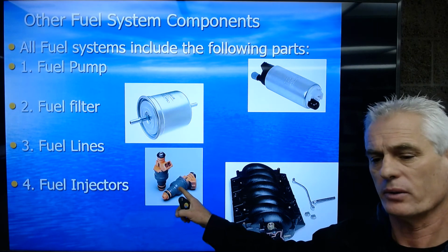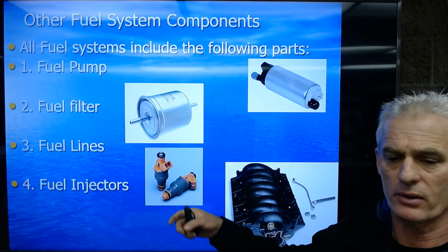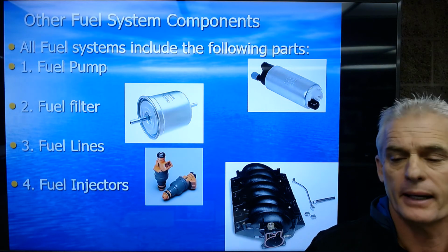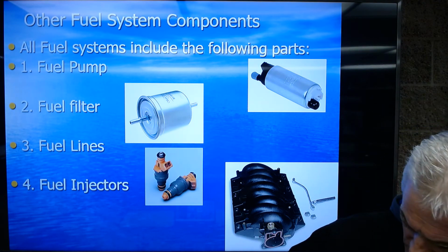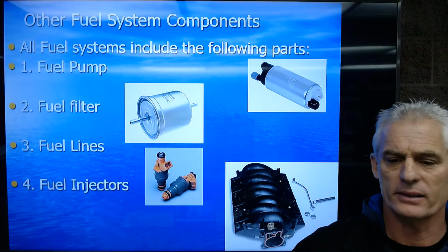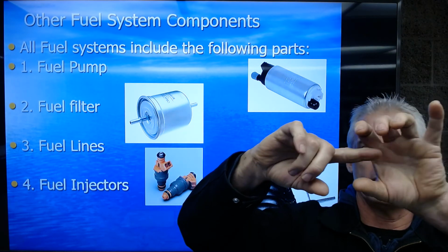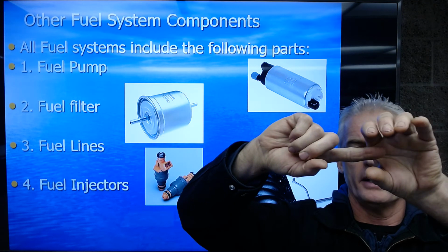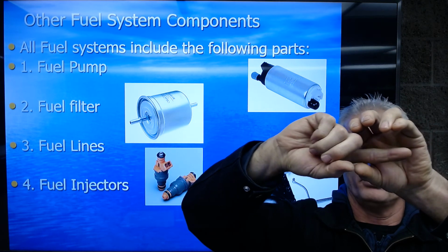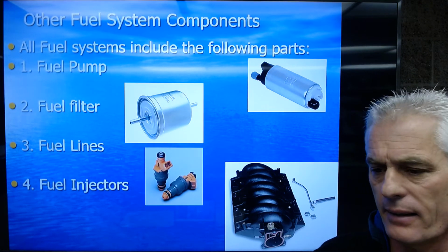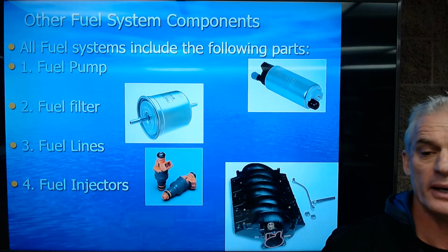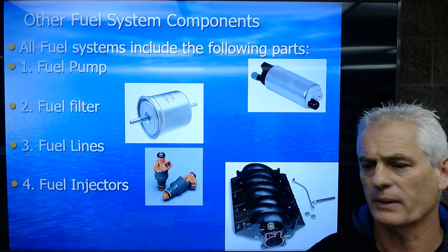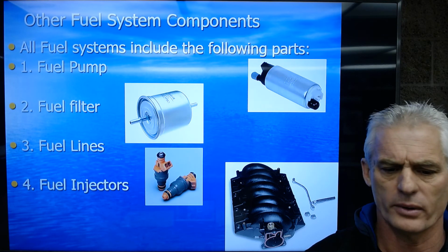They're little electrically operated solenoids that just have a coil and a plunger, and it lifts up to let fuel spray out. The really cool principle that the solenoid works on is electromagnetism. If my hand is a coiled wire, and this is a metal rod, and I offset it with a spring, and then I energize this coil, it'll pull the plunger in and center it in that magnetic field. So we're able to have this on-off kind of movement for all different types of mechanical applications.